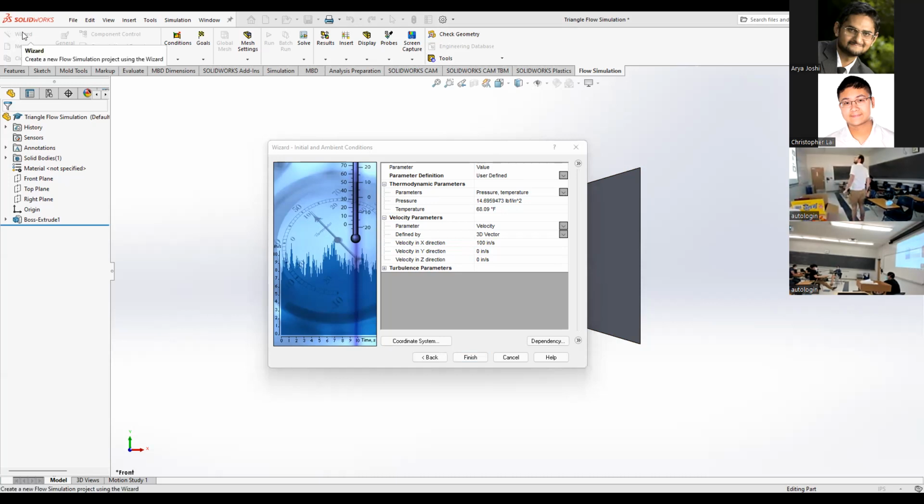If you press wizard up there, it's kind of grayed out right now, but if you click that, this box should show up. Basically choose a velocity. This is going to be an instantaneous velocity or the maximum velocity in our case, because when the Hyperloop pod accelerates, it's going to go from 0 to whatever maximum speed it's going to have.